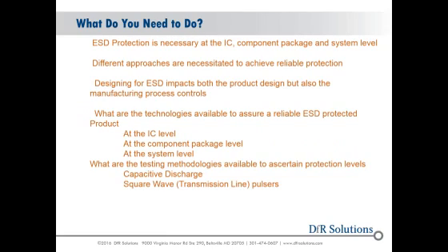There are different technologies available to assure a reliably ESD protected product at the device level, at the package level, and at the system level. And there are testing methodologies available to ascertain the true protection level that you have. These can be capacitive discharge or transmission line pulsar type systems.